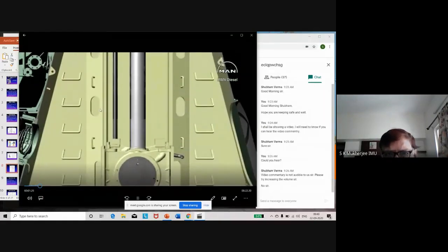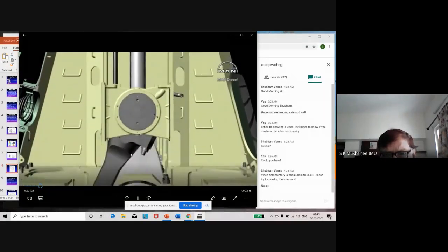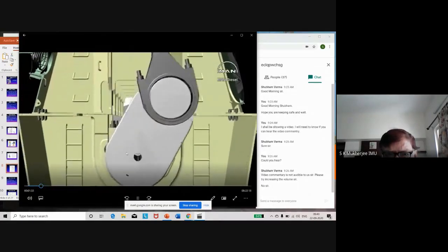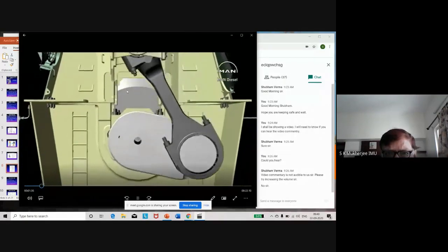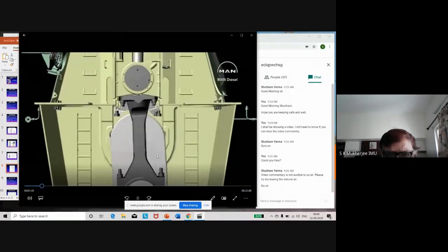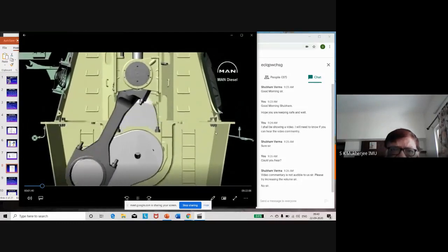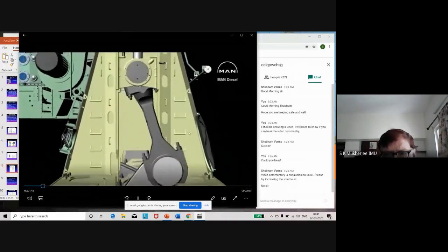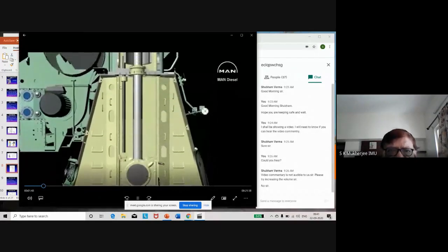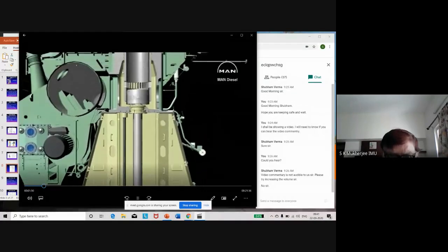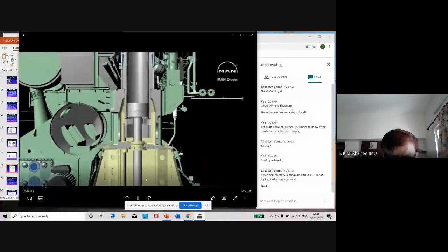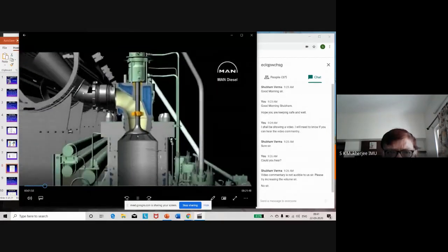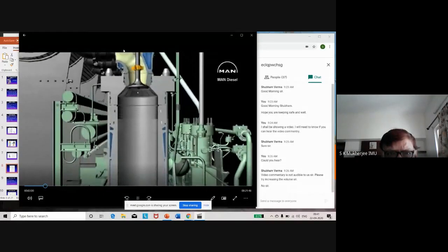And the crosshead is going in the two guides on the two sides. And that is the connecting rod, which is making angularity. This is the crankshaft. See, that's the other web over that side. And this is in this chamber. You see, this is the stuffing box which separates the under piston spaces from the crankcase spaces. All right. This is the exhaust passage.